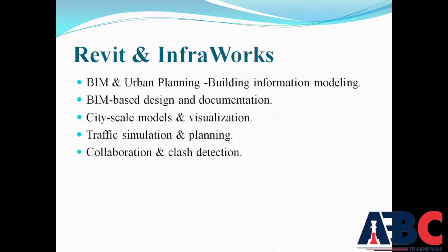Revit offers strong BIM collaboration features, like BIM 360, developed by Autodesk. Multiple team members can work on the same model, with cloud-based file sharing and version control, and clash detection can be done with Navisworks to avoid design conflicts before the project begins. So those are the kinds of features we can get from Revit.